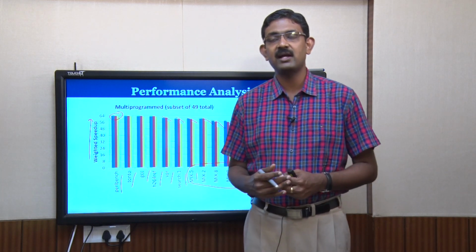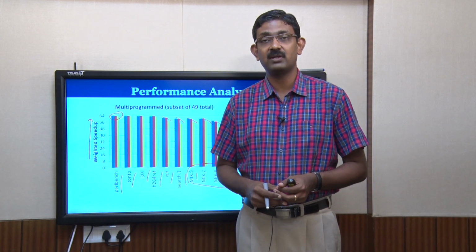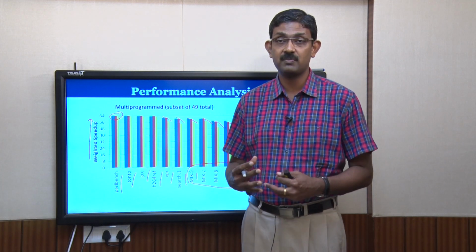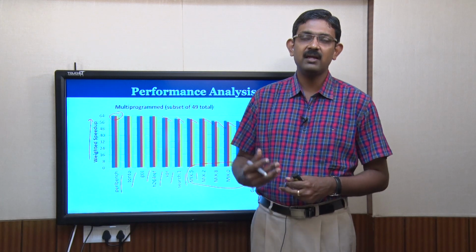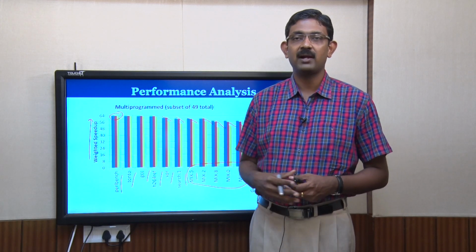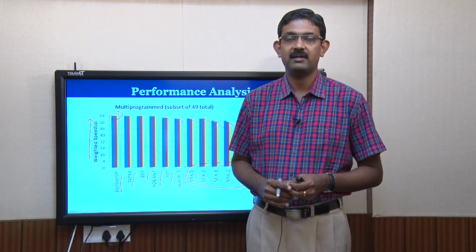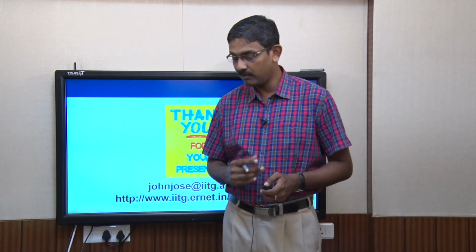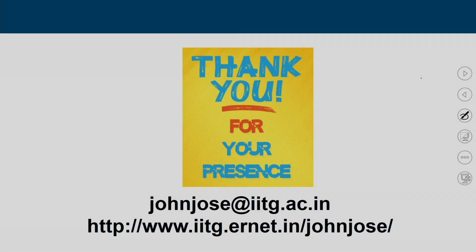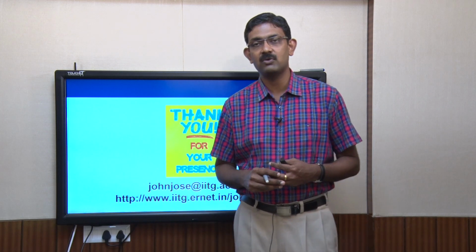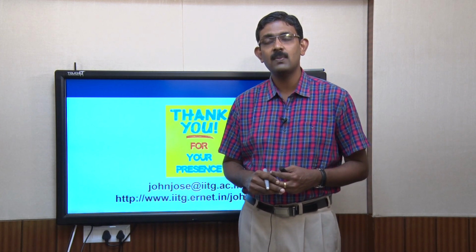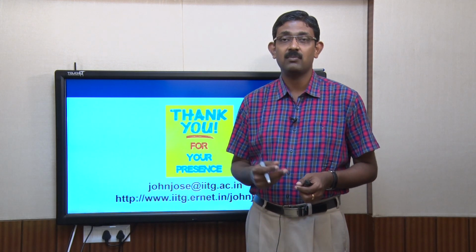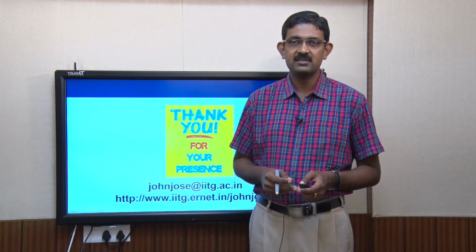In our next lecture we will try to see what the problems of bufferless deflection routers are. Of course, the main problem is that we are going to have a high deflection rate. Can we reduce the deflection rate by incorporating some kind of storage inside? So, with this we complete this lecture. We will continue with low power NoC designs, especially energy efficient NoC designs, by minimizing the number of buffers. So, with this I conclude.